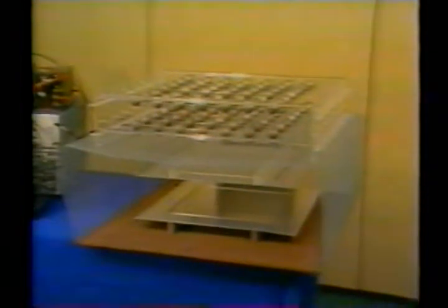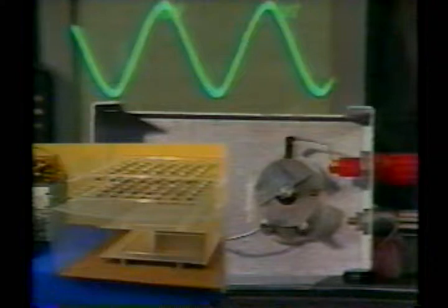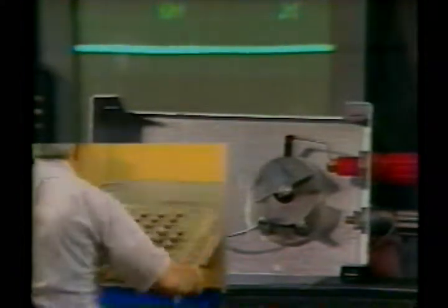Note the position of the tuning capacitor plates. If the capacitance has been increased to balance the bridge, the knob must be turned so that they have greater area of overlap. The balancing capacitance is increased, so the artificial dielectric does increase the capacitance of the plain parallel capacitor.